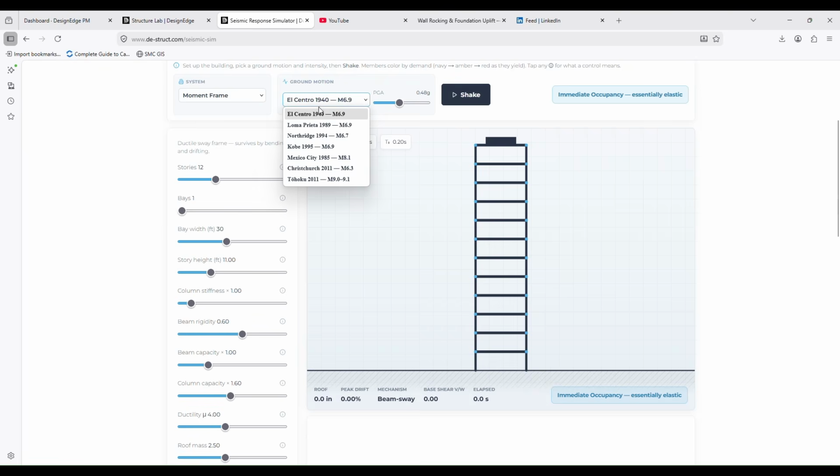But what's more important is understanding how the building is behaving and also the insights that the tool is giving you. It is taking some preliminary, basic-level fragility curves from FEMA P58, which just looks at what the drift fragility is for any general frame building. It's not even discretized between a moment frame, shear wall, or brace frame building. It's just using very average fragility curves that are give or take within the neighborhood or the bounds.